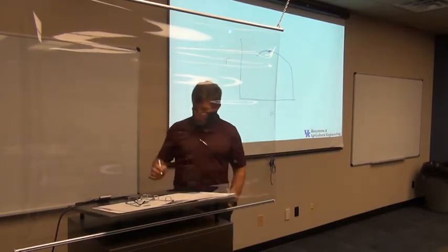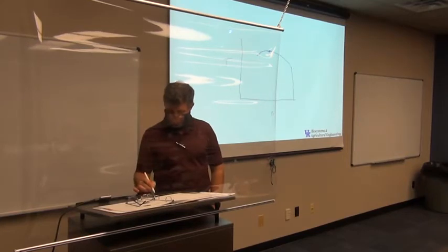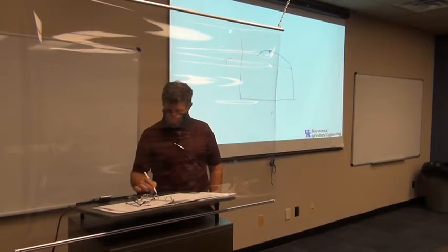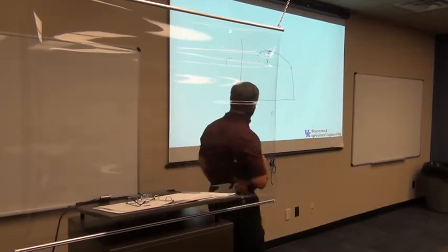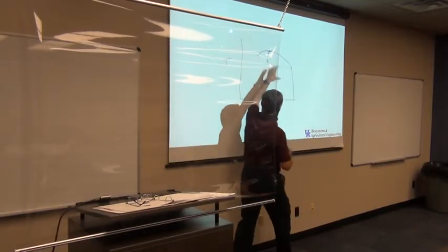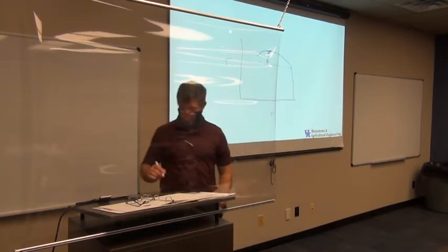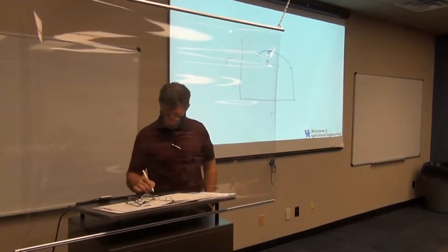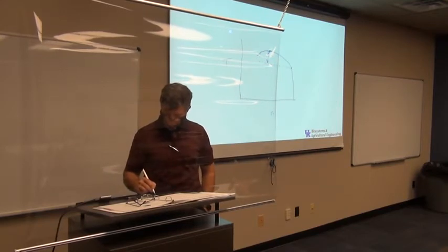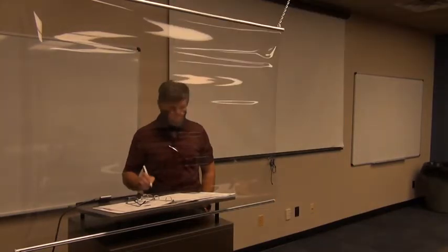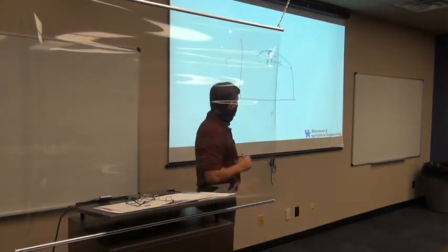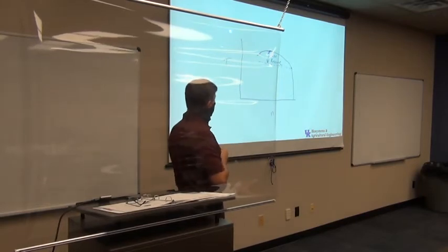Now, what the book talks about there, we actually measure this torque rise or torque increase. So if I go from this point over here, and I'm going to talk about what that is in just a second, we look at how much the torque increases from this point up to its maximum. That's what we call the torque rise or torque reserve. You'll see two different terms used, either rise or reserve. Okay. Torque rise or torque reserve, looking like that.